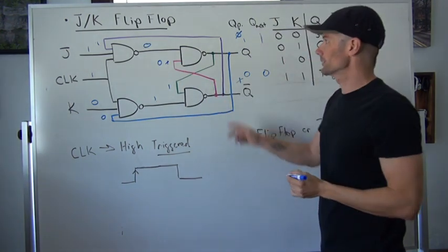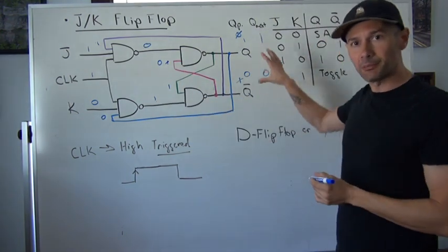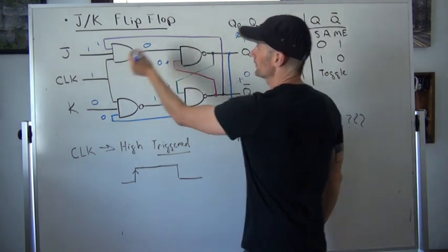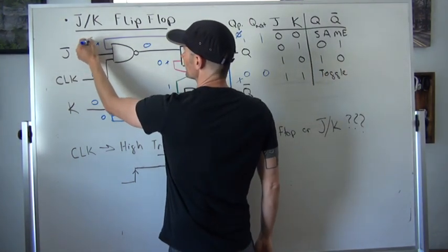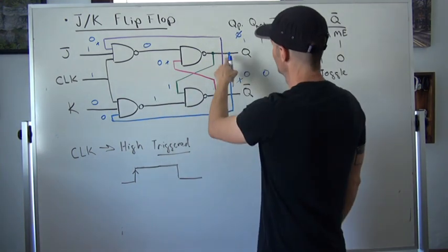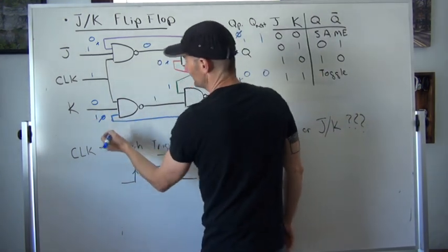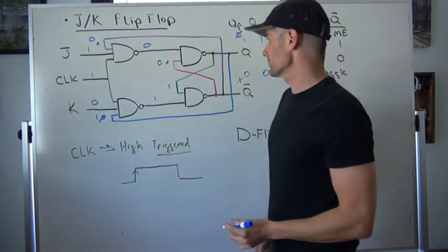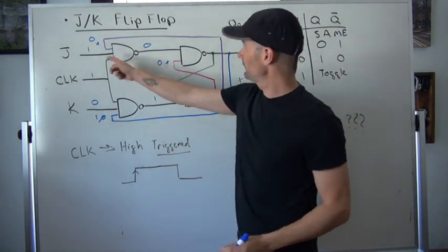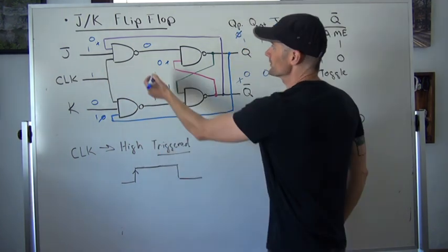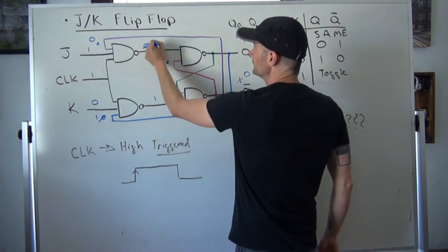Let's make sure we're consistent with all the outputs now being fed back to the input. So now we have a 0 that's been fed back up to here. And then sure enough, that 1 is being parsed all the way back to that output. So if we have 0, 1, and 1 all NANDed together, that turns this into a 1.